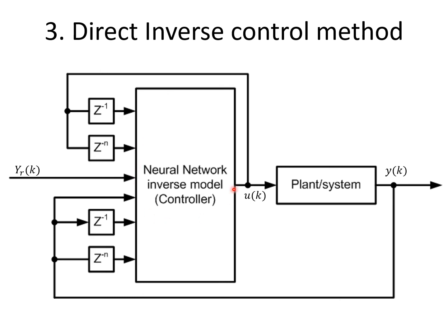And as I said before, in the real world, the controller is just an inverse of the model. A perfect controller is the perfect inverse model of the plant system. If you have the perfect inverse model of the plant system, you will get a perfect controller. So the better your training of your inverse model, the more accurate your inverse model, the more accurate the controller you're going to have in your system. Of course, you have disturbance and so on. You can use adaptive, or you can use the next method we see to adapt for that. But if you have a very straightforward system, with very little disturbance and very little noise, then you can implement this directly into the controller itself.